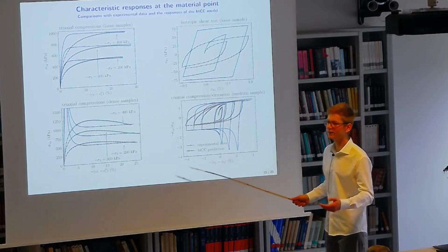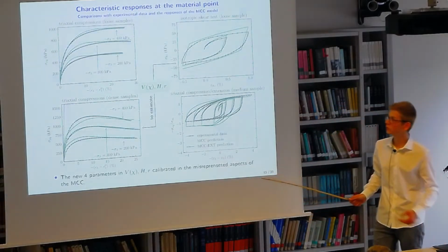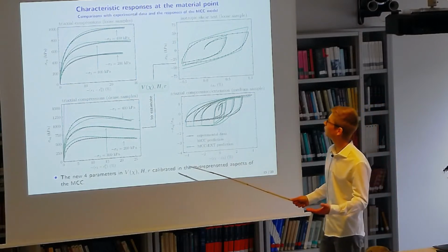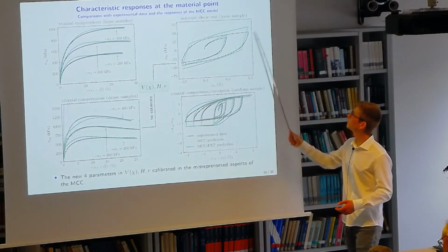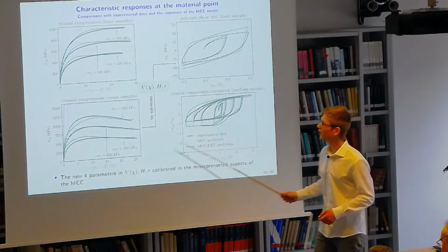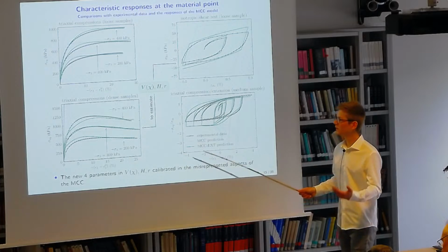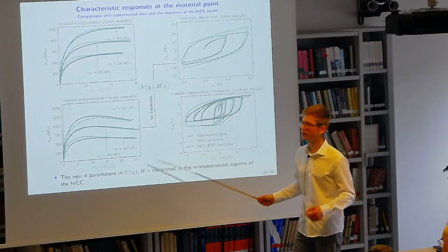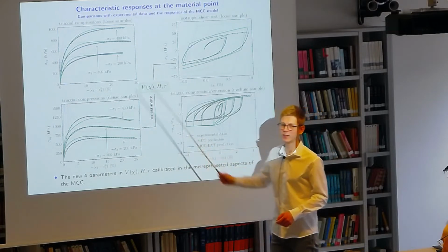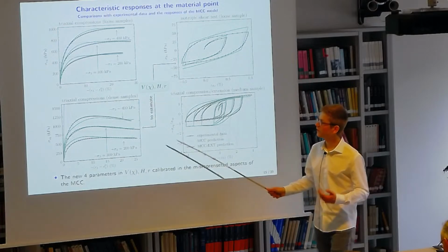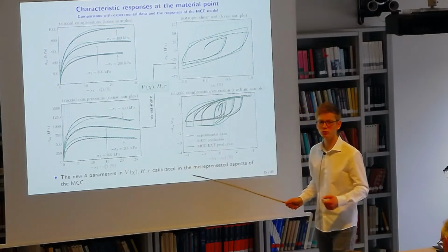Going back to the experimental comparison, you can see again with the blue lines the MCC prediction with the experimental data and some of its deficiencies. Next, our proposition in order to extend the prediction of the Cam-Clay model allows us to be more predictive both with regard to the hysteretic behavior during the cyclic shear tests, as well as the maximum equivalent stress and the softening evolution during triaxial compression of dense granular soils. You can observe that between blue and green line, you have the same asymptotic behavior. They have the same stress level. This reason lies in the expression of the hardening which have been introduced, which are nonlinear.